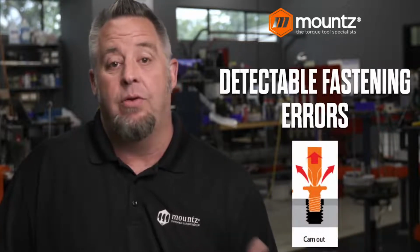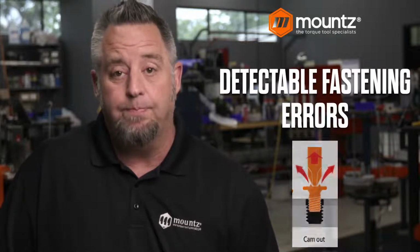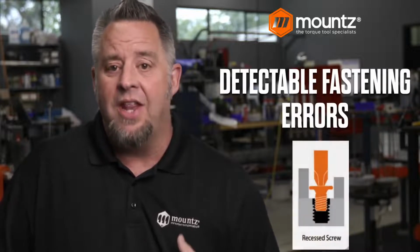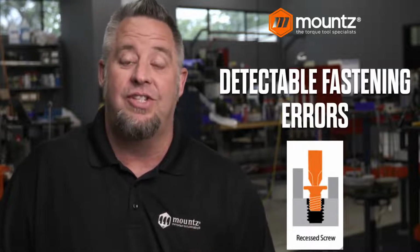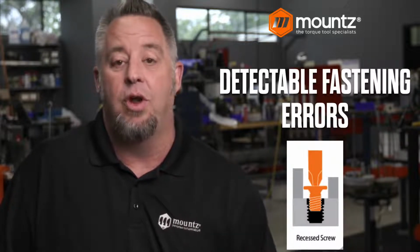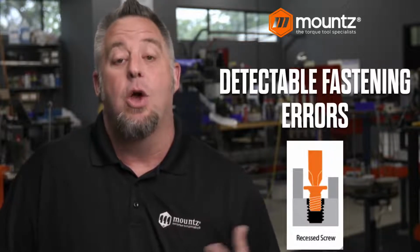And then if there's a cam out, again, this would be almost like a lifted type of fastener where the bit just lifts out and the operator lets go of the trigger. And then we can also detect if there is a stripped fastener as well. And then finally, if we're dealing in a situation where the operator necessarily can't see the fastener itself, so it is recessed and they're a little bit unsure of if that was done correctly or not, we can help detect all of those different types of errors in the event that the operator can't necessarily see what is going on with the fastener itself.